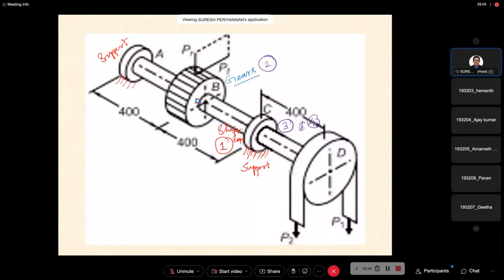In the bearings, we discuss journal bearings and ball bearings. Ball bearing or rolling bearing, all are the same. So ball bearing, I mean rolling bearing, or anti-friction bearing. In the journal bearing, the contact is sliding, surface contact, right? And roller bearing is line contact and ball bearing is point contact. So while transmitting power, while connected with the shaft, that's what we discussed.